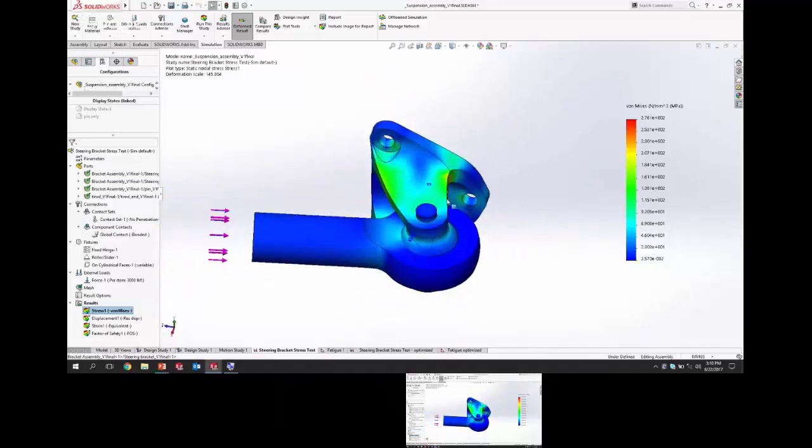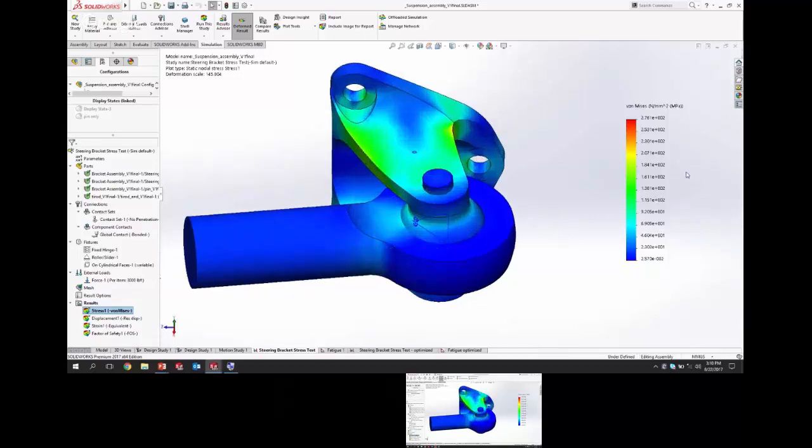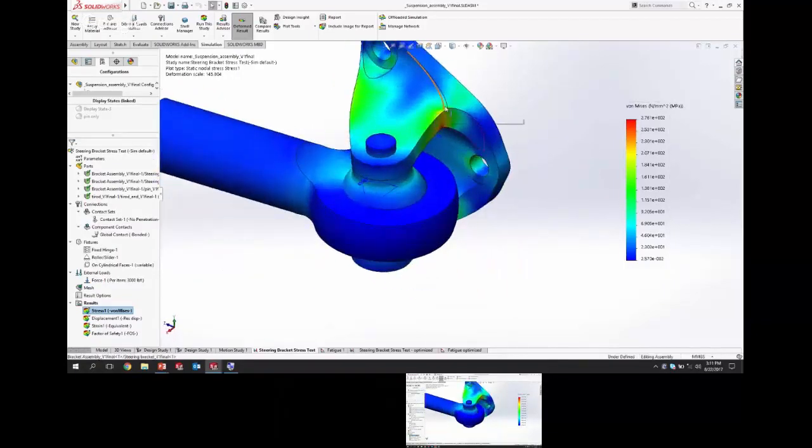Now, this is kind of a cool problem because it needs to last. Needs to have a given amount of durability. Okay, so we're well under. I think the tensile yield stress of this 4130 is about 560 megapascals, and we're sitting at about 276. So roughly half.